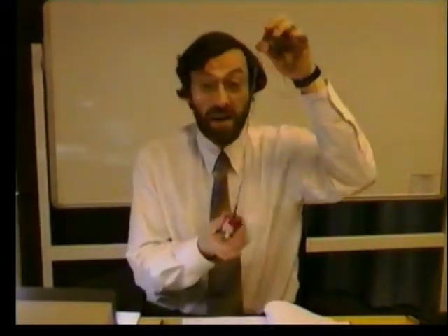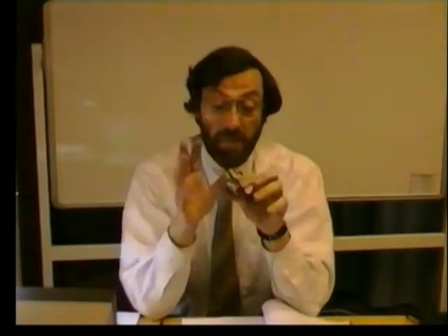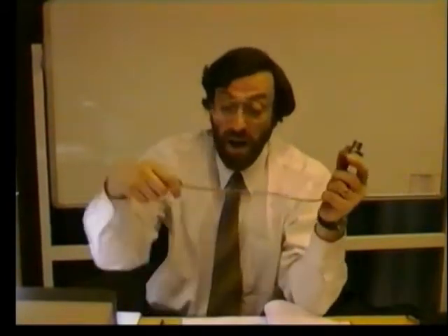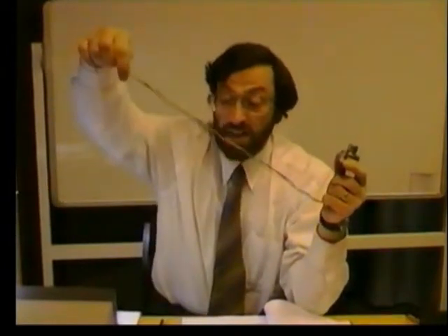It's a device where the transducer itself is connected directly to the computer by a set of wires. So a transmitter is a special class of transducer that combines both the transducer with the mechanism to transmit the information from the remote environment to the computer.